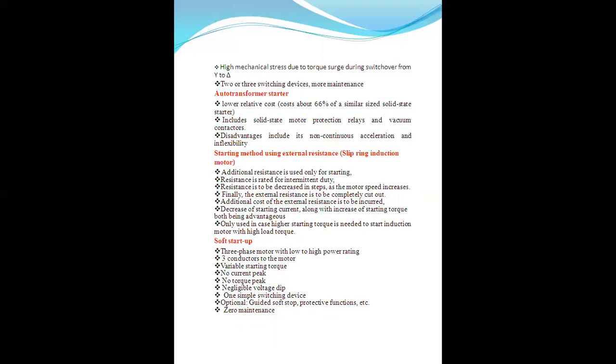The starting method using external resistance for an induction motor: additional resistance is used only for starting. The resistance is rated for intermittent duty. Resistance is decreased in steps as the motor speed increases.